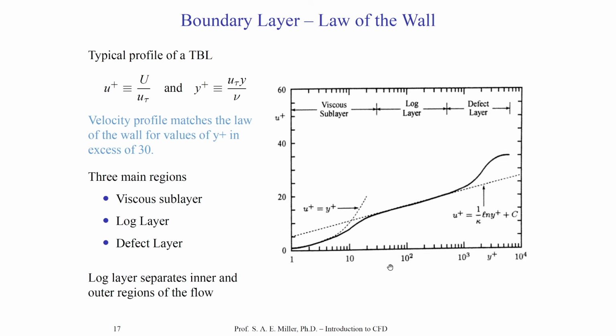You might be wondering why, as a practical user of CFD, you might care about this at all. Well, we'll be talking about that at length in later classes. But as you imagine, if we wanted to resolve the turbulent boundary layer to find the correct velocity profile, which would then be used to find the correct drag, the derivative of the velocity at the wall dictates the wall shear stress we will find, which dictates drag.